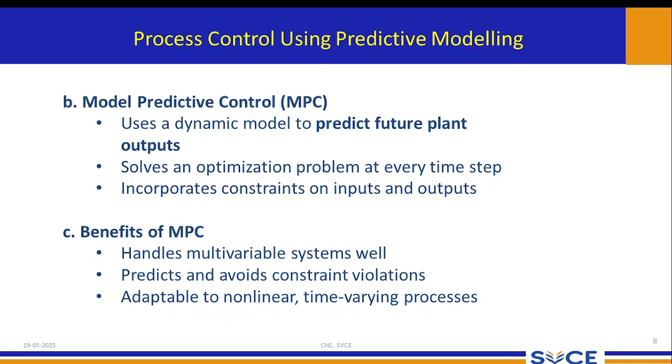So when I teach you model predictive control, we will be able to implement the variation and adjust accordingly. For example, in the spray dryer, I told you an additive will be added in order to avoid stickiness. How much amount of additive needs to be added in the spray dryer before the sample is injected into it? With predictive control, we can put a sensor and manipulate the variable so that if any deviation occurs, say the stickiness increases, the input value can vary and we can have control in a real-time scenario.